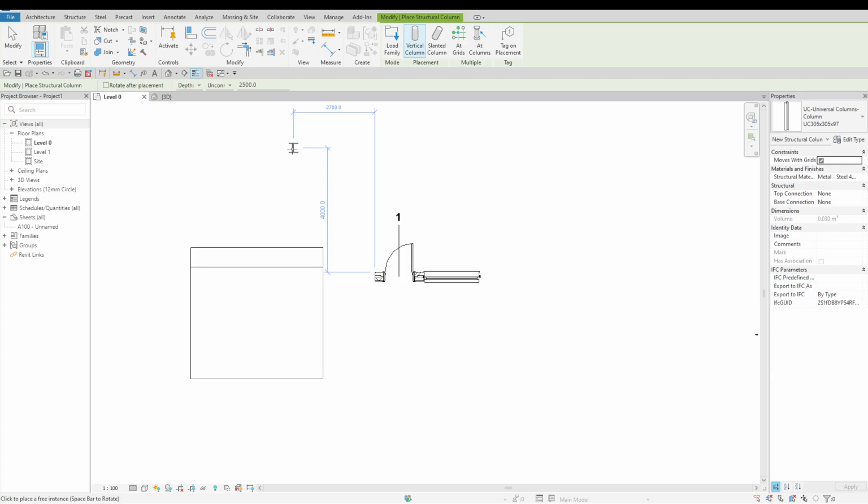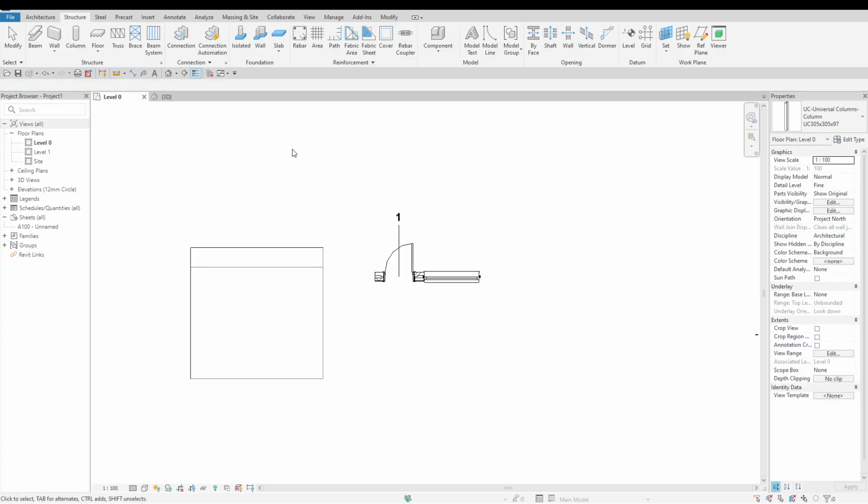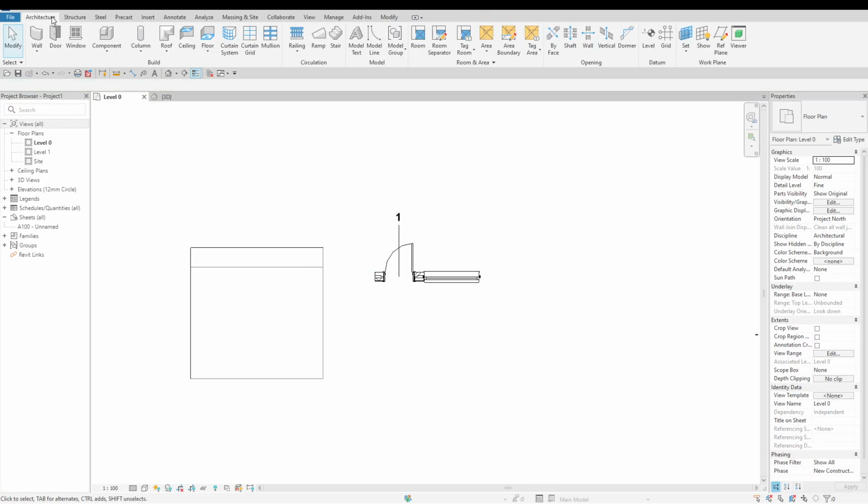The roof protects a building from the weather, provides insulation, contributes to structural stability, and enhances its appearance. It also aids in water drainage and helps preserve the building's materials. Revit offers several methods for creating roofs. Choose the method that best suits your design needs. You can create a roof from a building footprint, as an extrusion, or from a mass instance.